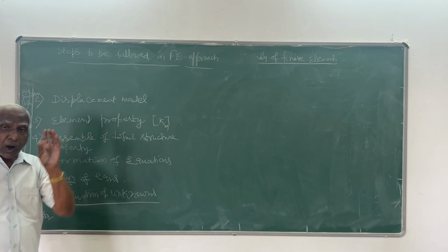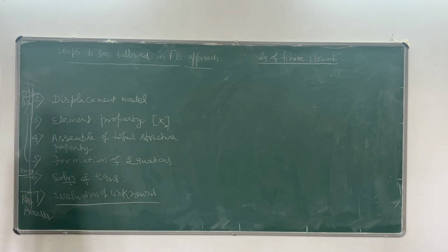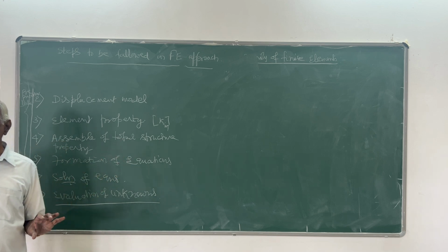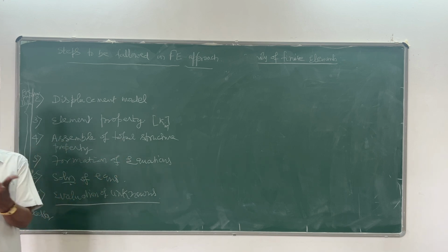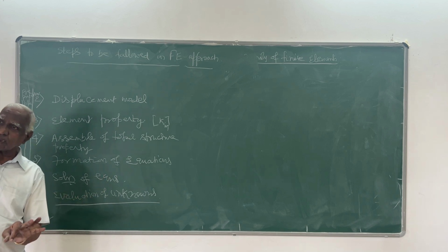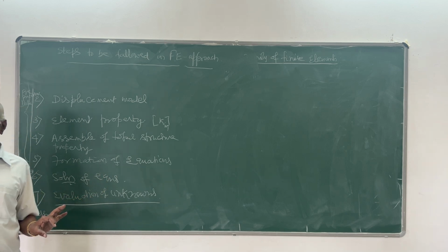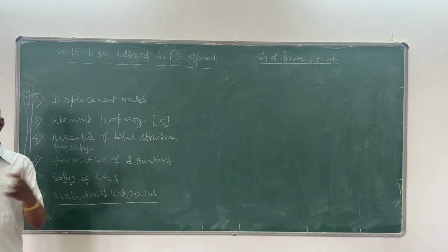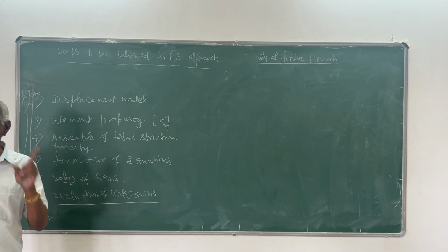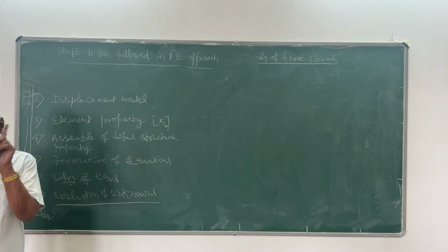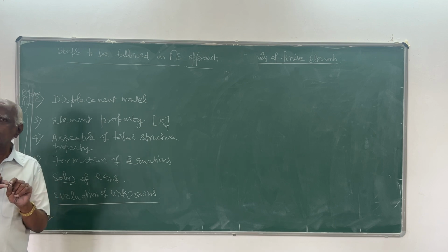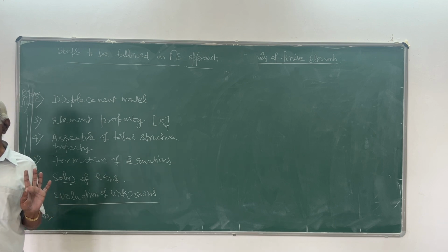So in bar type of problems, analysis of bars or spring elements, there will be only axial deformation, no other type. Even if it is inclined, it will be axial only. No question of any other displacement. It will be along the axis only in the case of bars. In the case of bar elements, the displacement is only along the axis of the element.